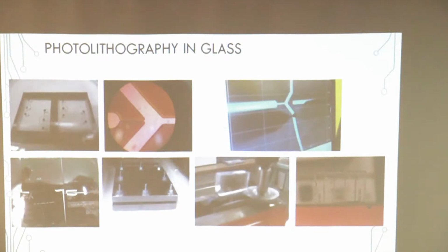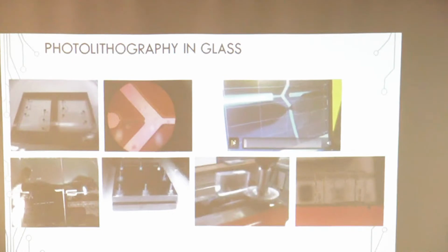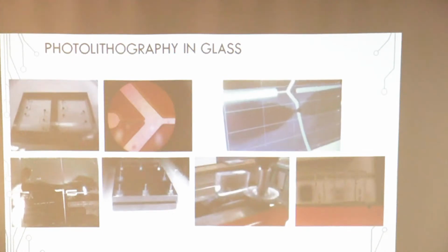After that, this is part of the fabrication of the microchip. Here with photolithography, we develop these chips, and as I told you, we create a master mold with a channel of 10 micrometers wide and 15 micrometers deep. We can see here in this video the profilometry study of the characterization of the channel.